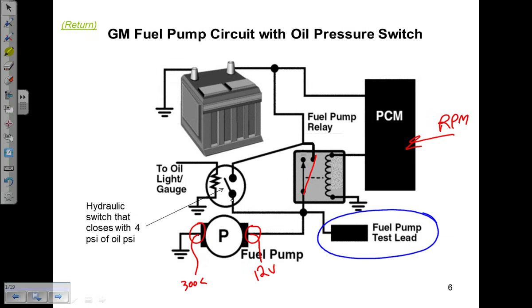Not to mention your buddy inside the car is pretty pissed at you because you're taking too long. He's got work to do, and you got him up in the air. So what we need to develop when it comes to fuel pressure testing is to be able to confidently energize the circuit manually, and then we don't have to crank the engine over anymore. We can do our pump, power, and ground checks without doing that.